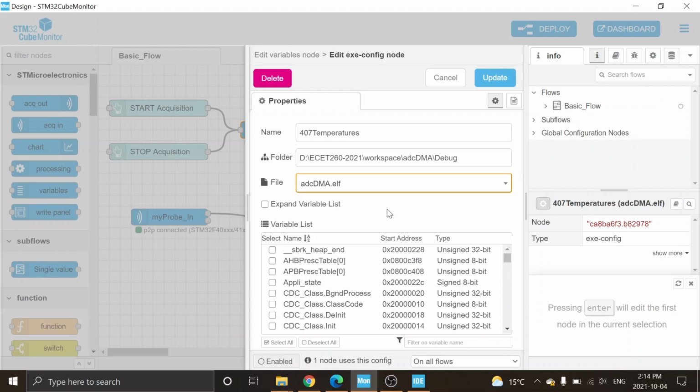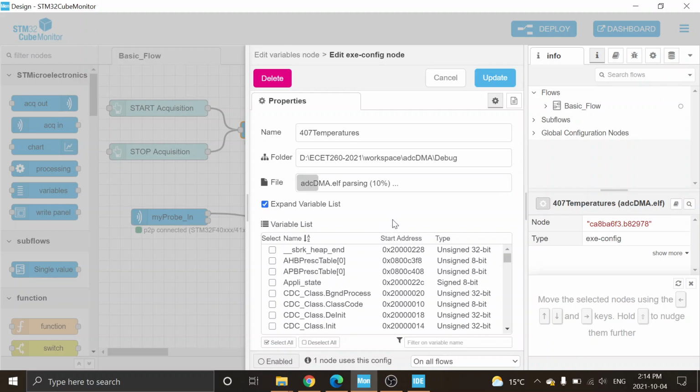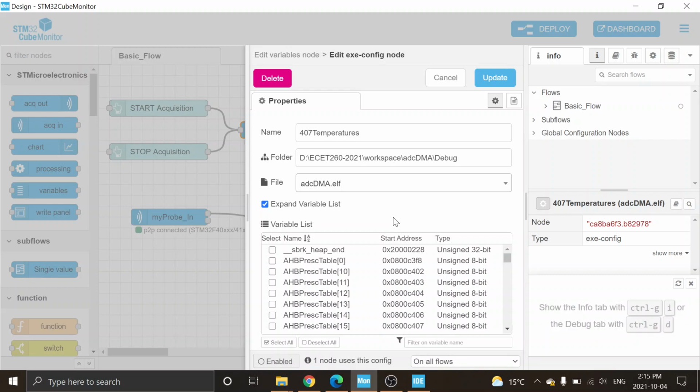And what it's looking for is the addresses of all the variables. And so most of the time, it's just good like this. But sometimes if you have variables, you might need to expand it, and it'll go through looking a little bit deeper. You have put your variables that we want to look at global, so it should be just in that list, and it's going to give you a better result than if it goes in and out of scope.